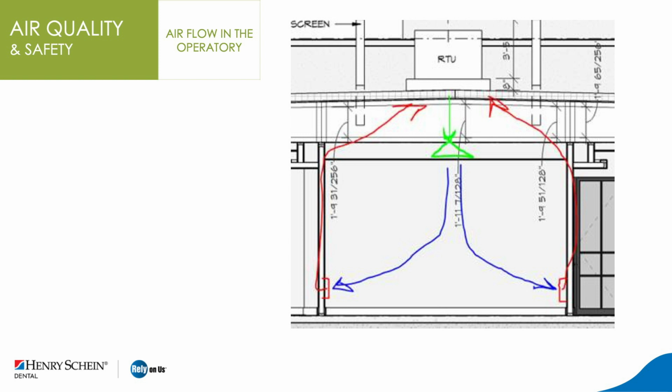And the concept is to drive the air and the particulates downward and away from the face of the staff. And this airflow discourages and reduces the continued aerosolization of viral particles and aerosol clouds inside the operatory. So consider using this methodology in each op in which aerosol is generated. And you can see the return air is indicated with the red arrows taking the recirculated contaminated air back up to the air handler and to be going through the filtering system.